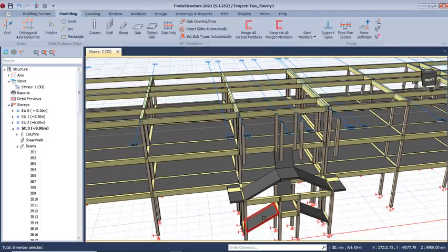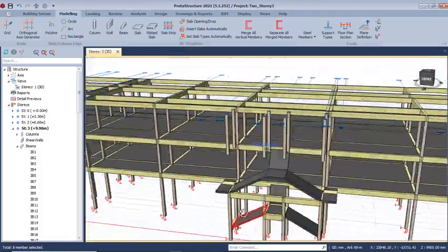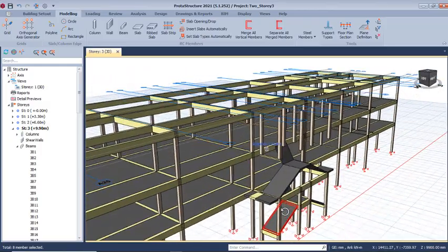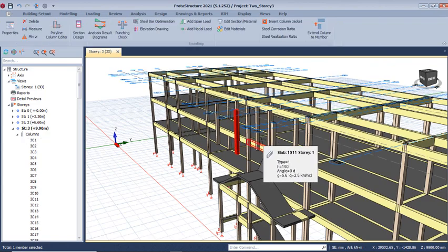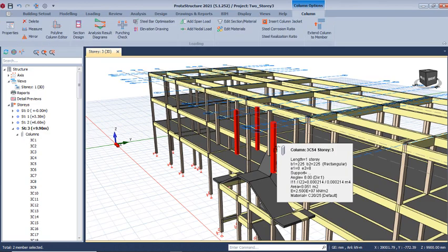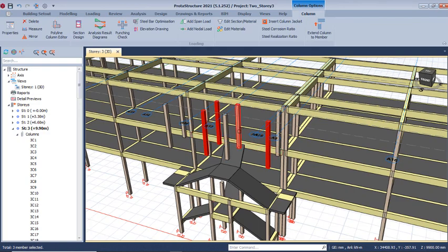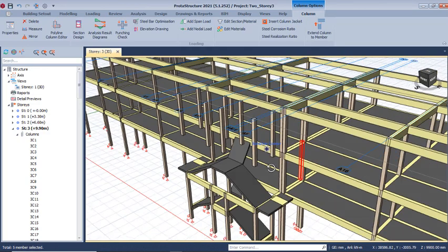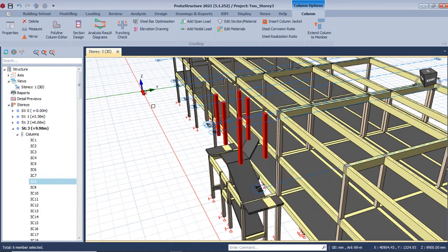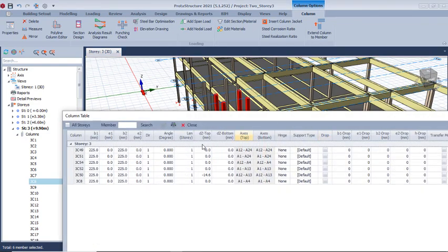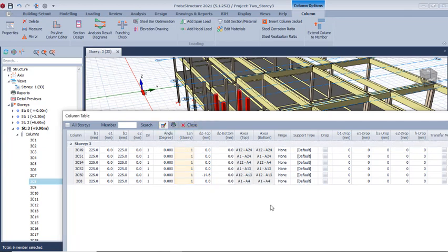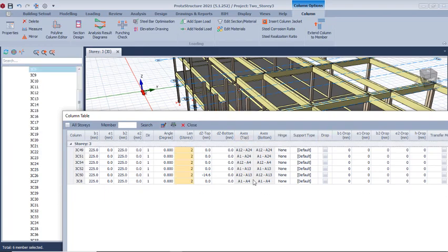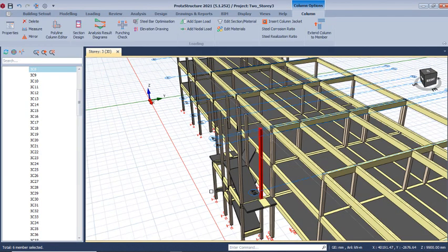Okay, all right, so at this point in time we are going to be selecting these ones. You see these ones that is standing alone, we select this one, hold the control key so you can select multiple of it like this. Rotate it so you can be able to see what you're doing. Okay, like this, right click and then click on its properties. So in this property dialog where you have story 1, you need to select it and then key into right there. Okay, click on the OK options and then everything is being adjusted successfully. Click on the close. So you have that.